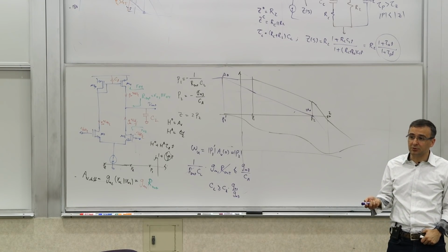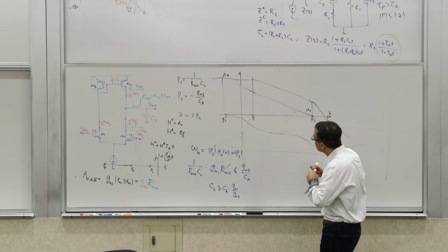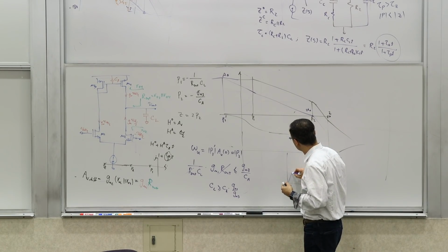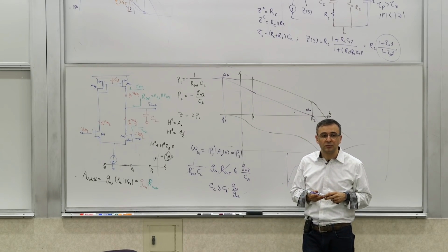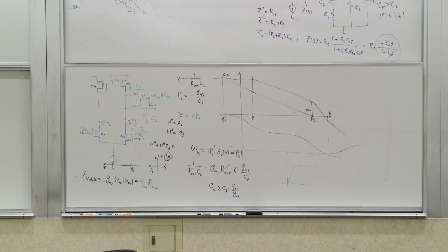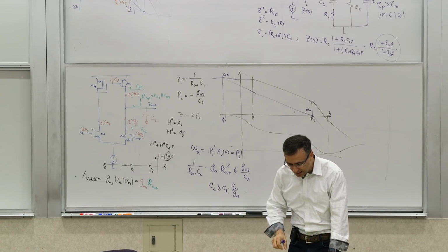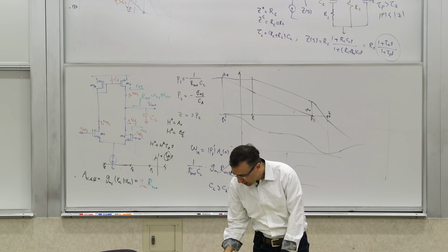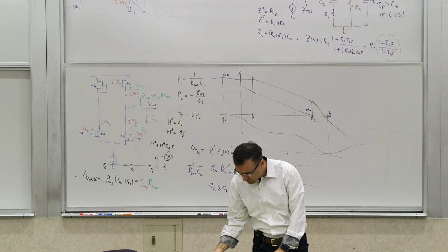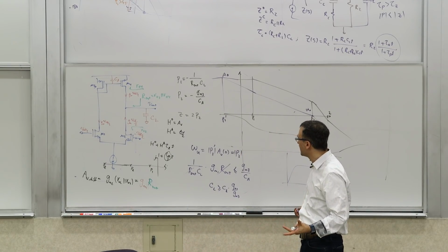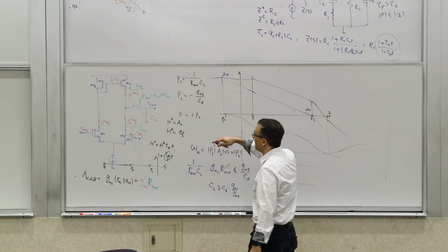Not only is it stable, but so is its time domain response. For example, if you shoot for a phase margin of 60 degrees, the time domain step response is also going to be pretty stable. It's not going to be ringing or showing an underdamped response. Okay, fine, that's for a basic single stage op amp with single transistors.